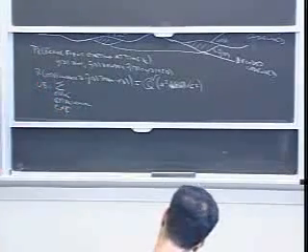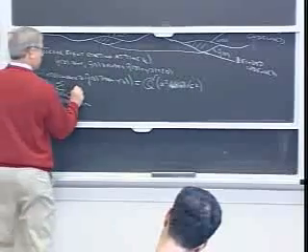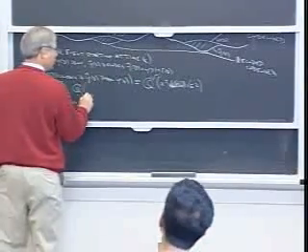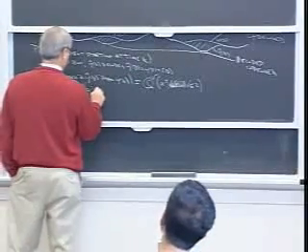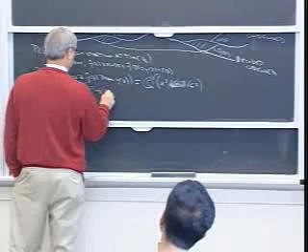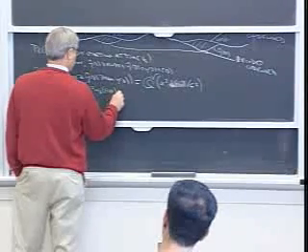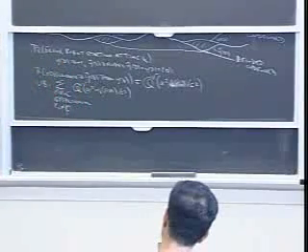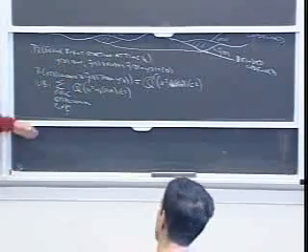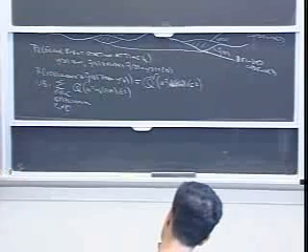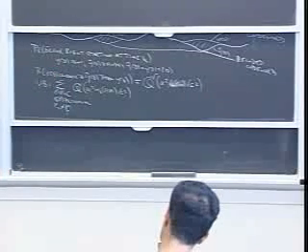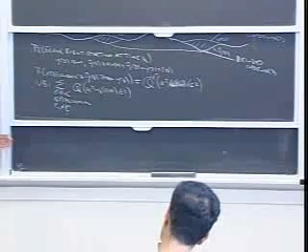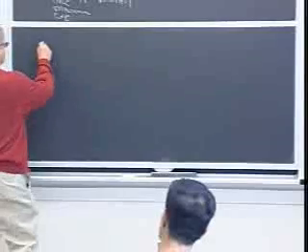I'm doing this very roughly, of Q of the square root of alpha squared times the Hamming weight of e of D over sigma squared. Just as before. So to get the union bound, we sum up over the weights of all sequences that start at time 0. Let's do it for our favorite example.